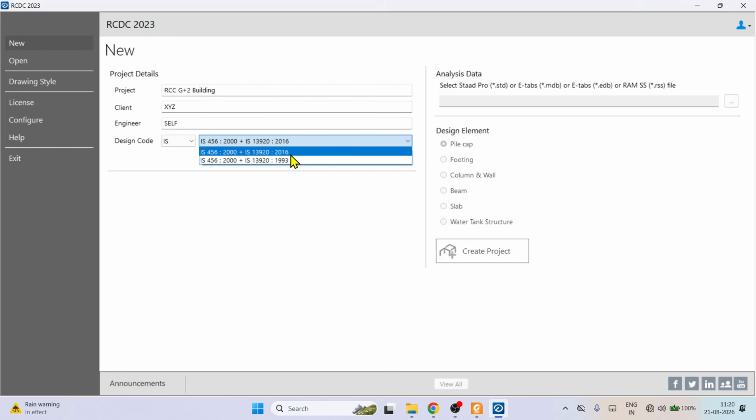Couplings can also be done; coupling means bearing welding as well. We can also give the lap, and if we are giving some kind of curtailment in place of bent-up bars, we have to take care of that, as all these details are given in IS 13920.